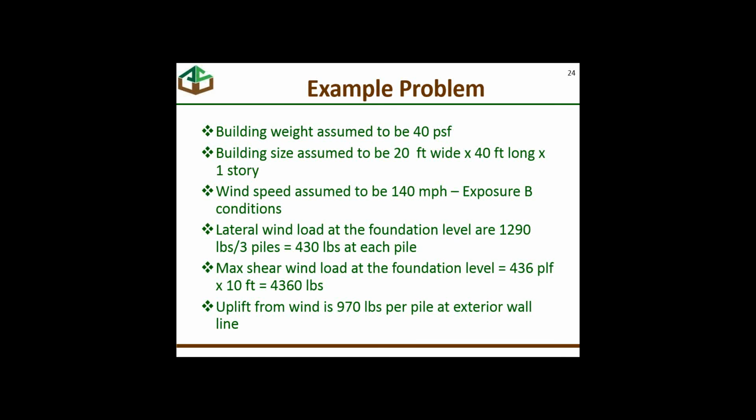We're going to have all the piles be the same size. We're going to drive them to all the same depth. We are going to make the connection between the piles and the beams or girders all the same. So whatever the number of bolts and whatever the diameter, they're going to be all the same. If we did anything different than that, we would have a mistake on our hands. I'm sure everybody would be familiar with how that would happen.